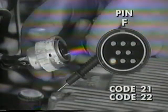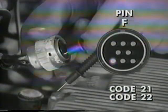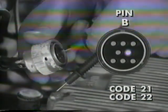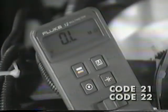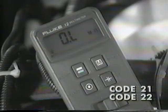So, if it's not within range, replace the harness. If it is in spec, check for abrasions that might be shorting the wiring harness to ground. Then, connect one probe to a good chassis ground and use the other to probe pin F for code 21 or B for code 22. The reading should be open or infinity.